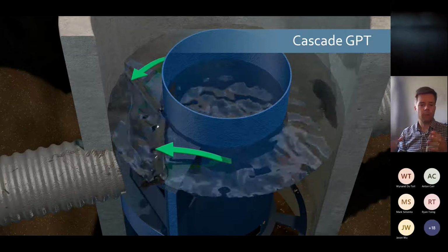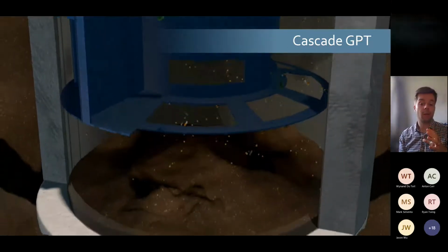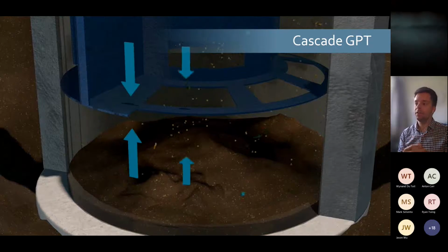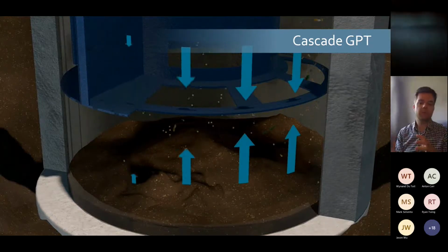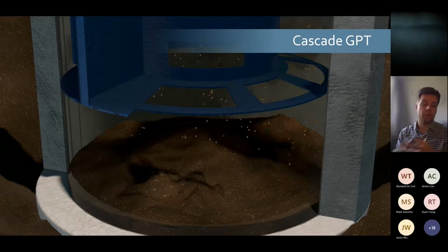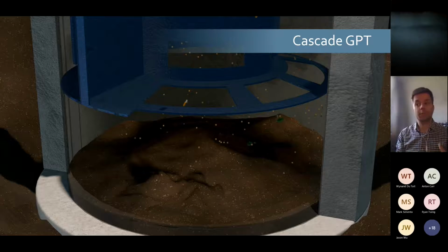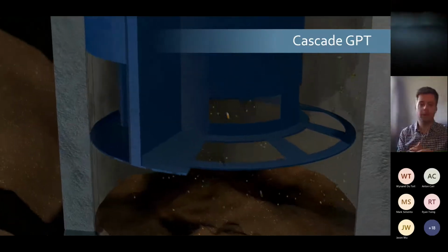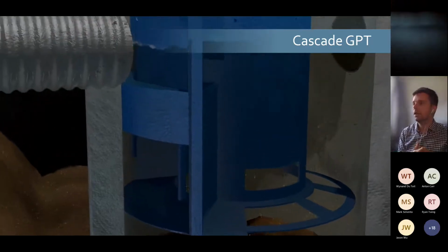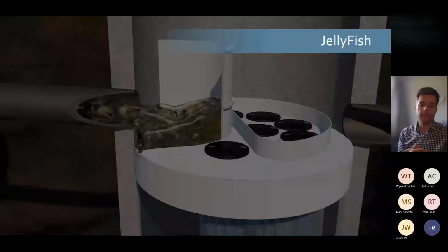With a lot of gross pollutant traps, the devices have to be very deep to prevent rescouring of previously settled out media. This skirt equalizes the pressure and allows the sump to be shallower than other treatment devices for the same amount of storage. So we're at roughly, say, 3.5 meters deep versus 4.5 meters or 5 meters deep for other comparable devices. As the water then drains down, there's a permanent water level in the device.